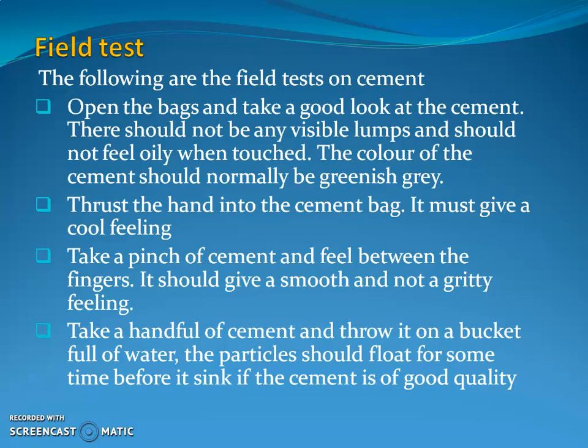Following are the field tests on the cement as given in the slide. First test is to open the bag and take a good look at the cement. There should not be any visible lump and it should not feel oily when touched. The color of the cement should normally be greenish grey. If all these criteria are satisfied, then the cement is of good quality.